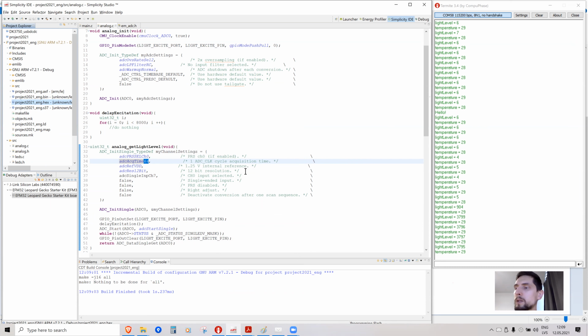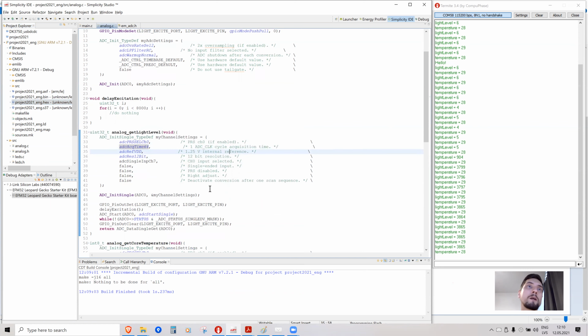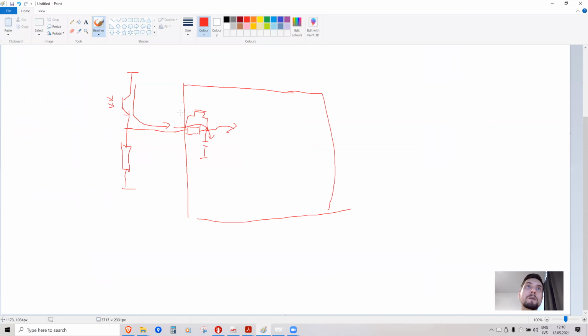And now what we need to do is we can do some other filtering as well. So the first step in signal filtering is having some RC filter to filter out some noise, but you have to wait RC time constant time for this capacitor to charge up to the corresponding signal level.